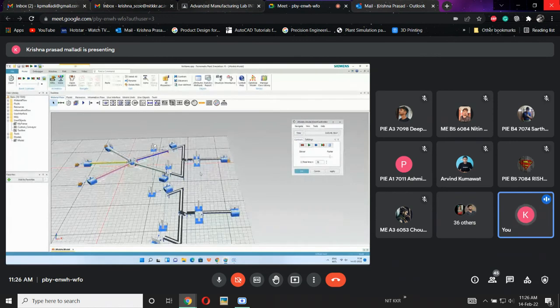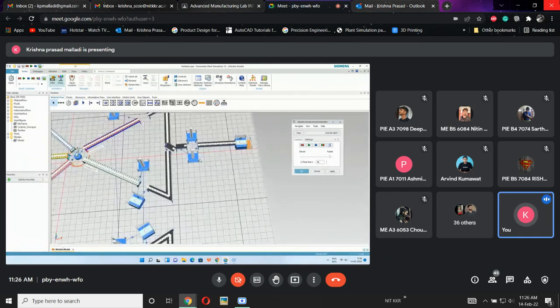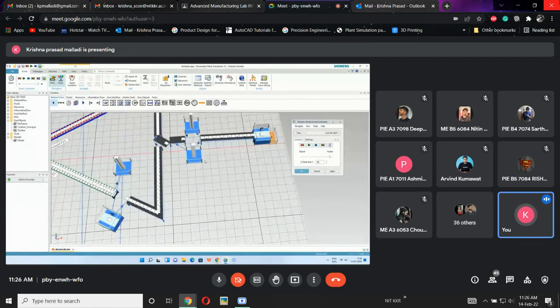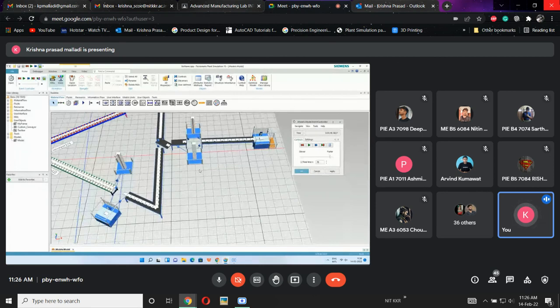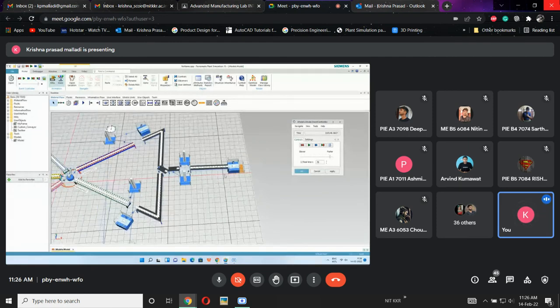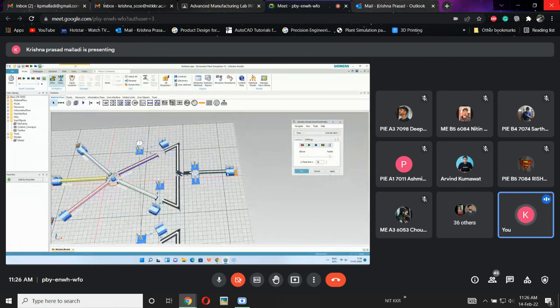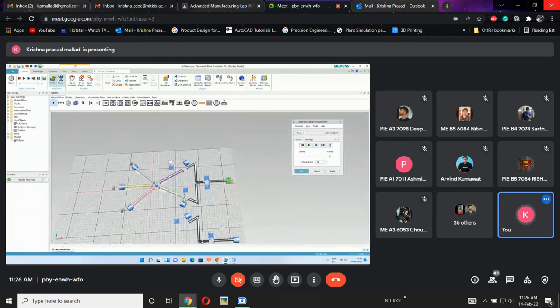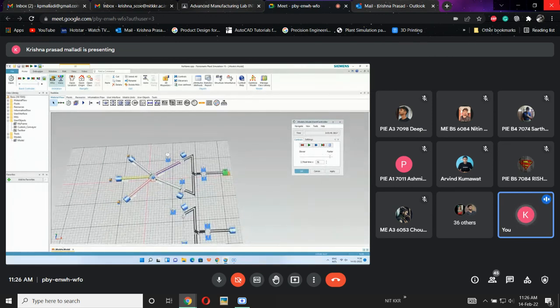Like I can add a process and check what alternative process I can adopt. That is what exactly we can be doing in this Plant Simulation. Initially we need to work with buffers only. So once the buffer is full, even after utilizing some 4 or 5 buffers, like here I am using 2 buffers, still if it is not matching, then I can propose to them: even though you are using 3 or 5, this is having a blockage. So the only option is to increase these machines, or we need to project some different solutions. Clear with this buffer? We'll be discussing this optimization in the later phases. Don't worry about this optimization part.